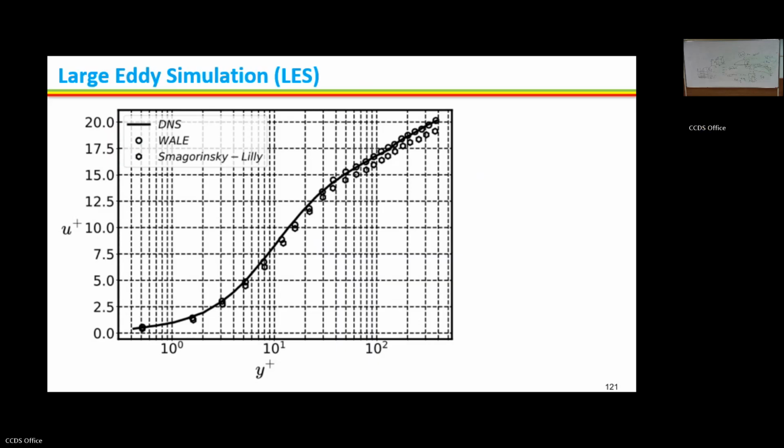Then these things, the LES, it seems quite relatively easy compared to the RANS, right? But why is it so difficult? Any idea? In the computation, we have minimal approximation. In the RANS, we have a lot of approximation. The third order correlation coefficients were assumed in terms of the equivalent diffusion. We have closure coefficients. From experimental findings we fix and calibrate those closure coefficients.